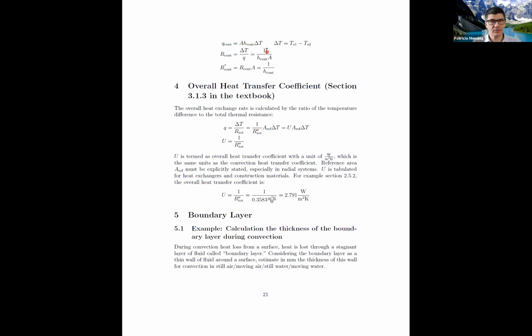So whatever the circuit is, whether it's a circuit for pipes inside a heat exchanger that has fouling inside and outside, or heat losses in a house, or pretty much any other problem that is in steady state, and at this stage we're talking about 1D, in all these cases the rate of heat transfer is proportional to the temperature difference between the two ends of this equivalent circuit.